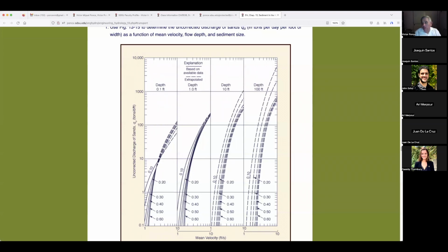And this is interesting, the laboratory. How do you measure sediment size? If you were doing this from a geotechnical engineering standpoint, you would use sieving. But the hydraulic engineers don't like that because it's too time consuming and the accuracy is really not absolutely necessary. So they use the so-called visual accumulation tube, which we are going to briefly talk about later on when we get to the area of measurements. The visual accumulation tube was developed in 1955, and I believe it was Colby also that had something to do with it. I could be wrong on that, but we'll go back to the original reference on the visual accumulation tube, 1955. So with that, we determine the diameter, the D50.